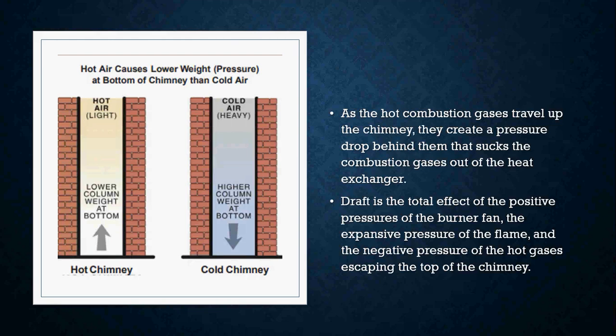One thing that we always think about when we're thinking about draft is to remember that cold air falls. Cold air is heavier, so it's going to sink to the bottom first. Warm air is going to rise. So in order for us to create that draft, we have to definitely change the temperature of our chimney and flue pipe in order to get that draft going.